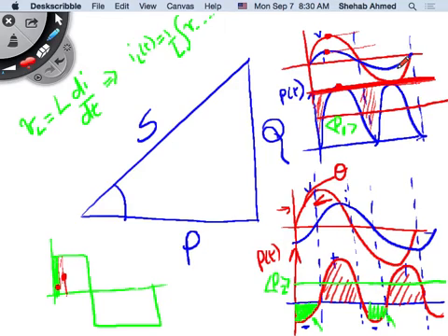But if I am transferring a huge amount of power, and I decrease the voltage, P equals V times I, right? So if I decrease the voltage from a safety perspective, what's going to happen to the current? For the same amount of power, it will increase considerably, right? And then, how about losses?